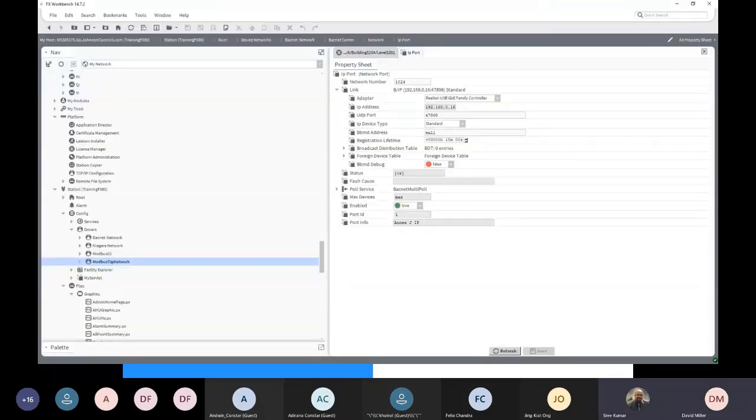Yep. Okay. So, I have a question, David. Can I have 2 COM ports as standby in one FX80 for the Modbus? Have 2 and switch between when there's a problem. Sorry, say that again. Can you have 2 Modbus COM ports in one FX80? Yeah. For example, if I'm using COM3 as a Modbus, then I get another expansion module for a standby COM port. Then after that, if my COM3 has a problem, I can switch to another COM.